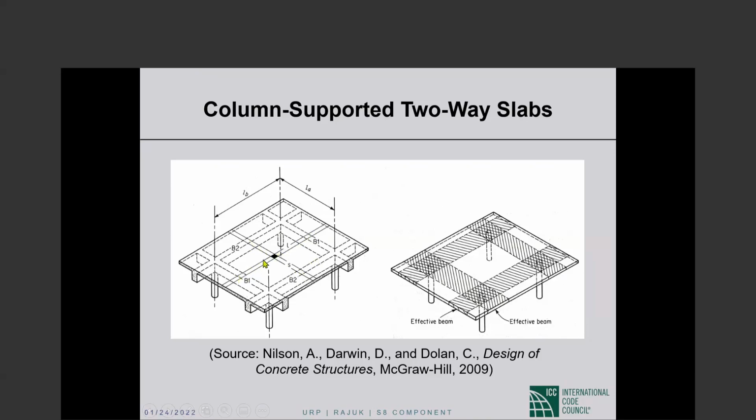Now, the 40% of the slab loads that are transferred by bending in the long direction, those loads are transferred to beams B1, which span in the short direction. Okay, so 60% of the load on the slab is transferred by bending of the slab strips spanning in the short direction, and the remaining 40% of the load on the slab is transferred by the beams bending in the short direction to the supporting beams.